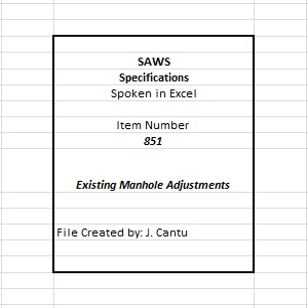851.7 Payment. The work performed as described by this item will be paid for at the contract unit price bid per manhole for existing manhole adjustment, which price shall be full compensation for all excavation, including saw cutting of surfaces as required, surface restoration, installation of all-weather surface, asphalt repairs as per City of San Antonio specifications, reinforced concrete, and disposal of material excavated, for furnishing and placing all materials and for all labor, tools, equipment, and incidentals necessary to complete the work.